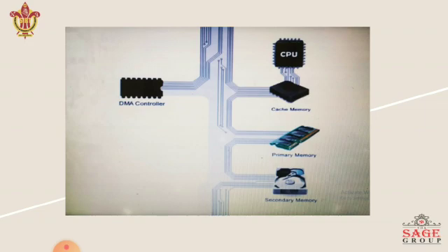Can we have some strategy to overcome this problem? Certainly, yes. One of the most basic techniques is to let the CPU offload intensive memory access tasks to another component called a DMA controller. This approach frees the CPU from memory-bound tasks and provides more cycles to CPU-bound tasks, for which it is better suited.